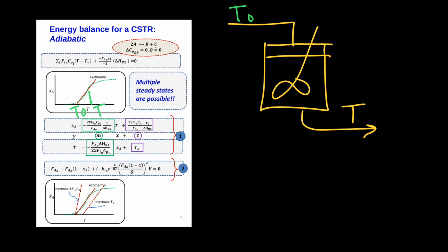An even more precarious scenario can arise if there's a disturbance that causes the reaction to ignite. We call it moving past its ignition point. So this is the inlet temperature, and it operates there at a mild temperature T and everything in your vessel is still nice in the liquid state.